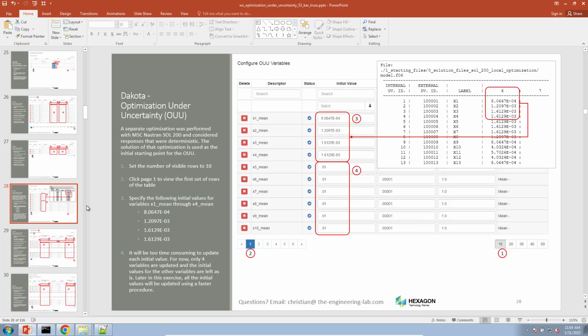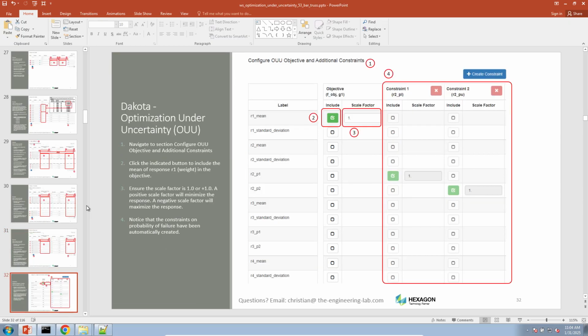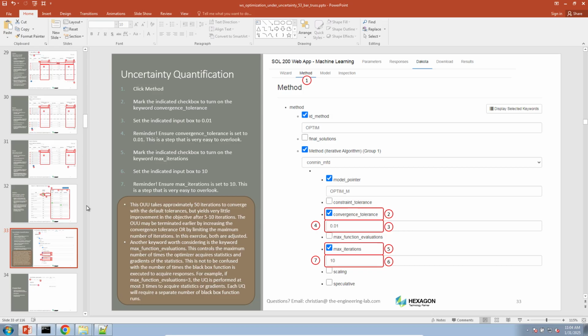Okay, so let me glance through the slides just to make sure everything looks okay. Okay, everything looks like it's going according to plan. Here, we're going to make some modifications to the optimization. So here, sometimes the optimizer will drag on. This could be because the convergence tolerance is too strict. You could alleviate or address this by terminating the optimization after a certain number of cycles.